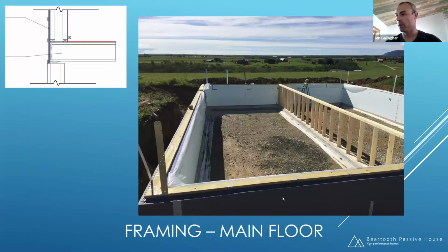So framing the main floor, like I mentioned, we've got a stem wall here. The nice thing with not having the crawl space be conditioned and be part of the air barrier is that I didn't have to worry about transitioning out and around my floor joists and air sealing my crawl space. So that was really, really nice.